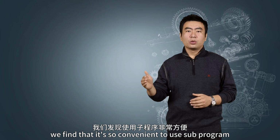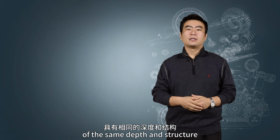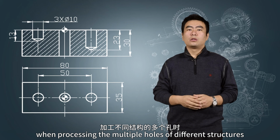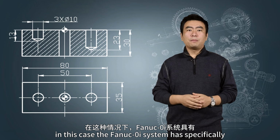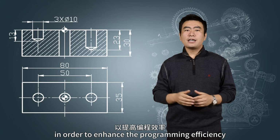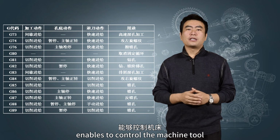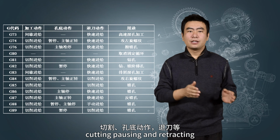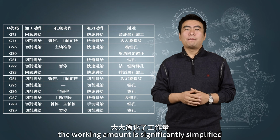In this case, we find that it's so convenient to use a sub-program to process multiple holes of the same depth and structure. But this way is not helpful when processing multiple holes of different structures. In this case, the FANUC 0i system has specifically designed a set of fixed loop instructions for hole processing in order to enhance programming efficiency. Just one fixed loop instruction can control the machine tool to consecutively complete the actions of locating, cutting, pausing, and retracting. By this way, the workload is significantly simplified.